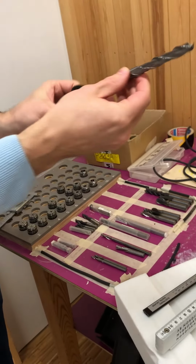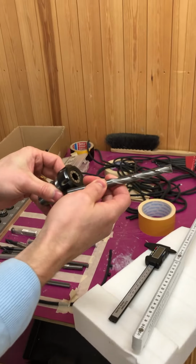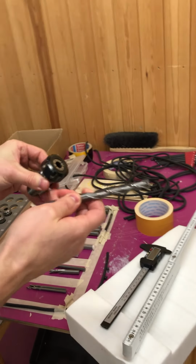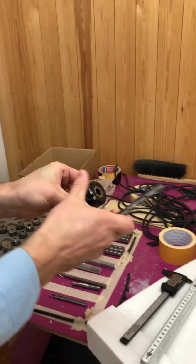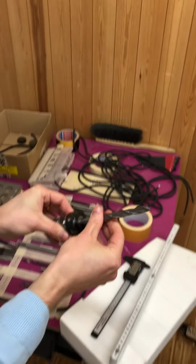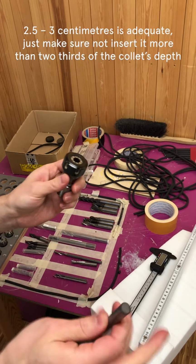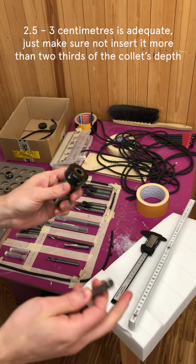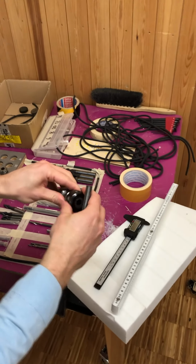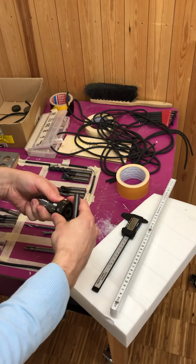And then we take the end mill, and we can just make sure that this is like so. It was too hard. Yeah, but that is good. And then we insert it no more than 2.5 centimeters, somewhere around there. I can show you why. I think that I actually showed you before, perhaps not consciously.